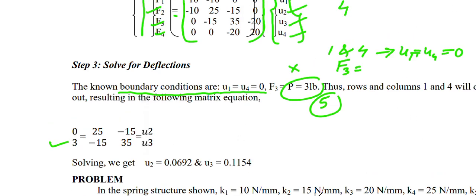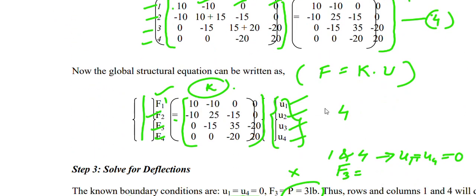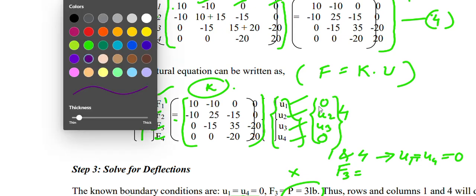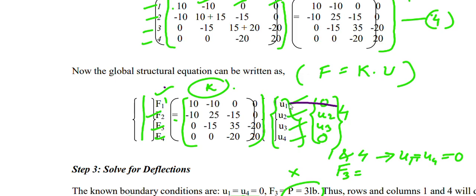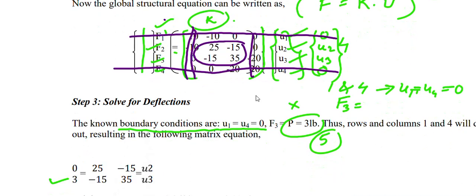Okay, so once the boundary condition is applied here, so there will be next elimination method. So how will be apply the boundary condition? For example, u1 u4 is 0 and u2 u3 you have to remains unknown. Okay, now after that here this row, entire this row and their column, means first row first column, this column will be eliminated. Now last row and the last column will be eliminated. What will be the remaining? Only this matrix. Okay, that only we have written. There will be force F2 and F3. Okay, so F2 there will be no force, so taken as 0.